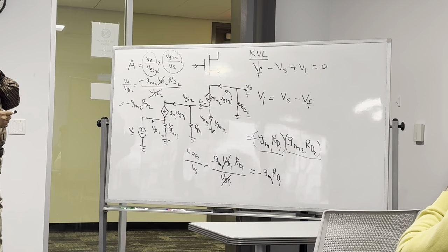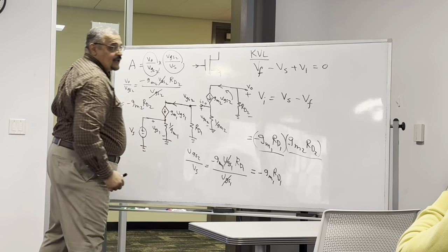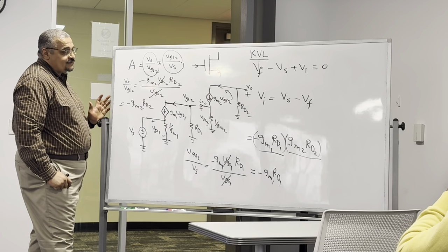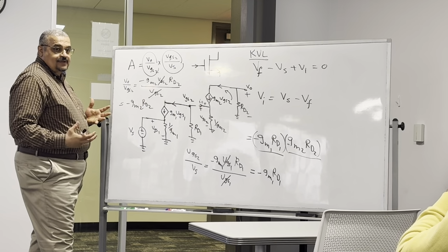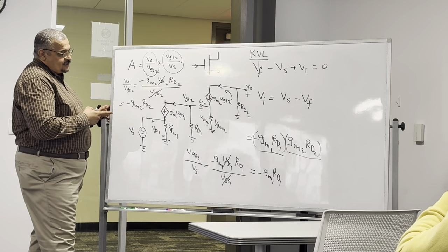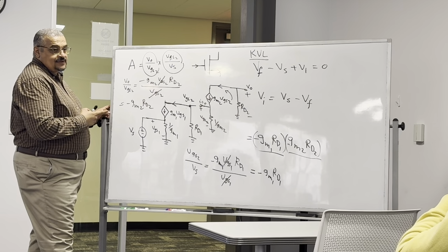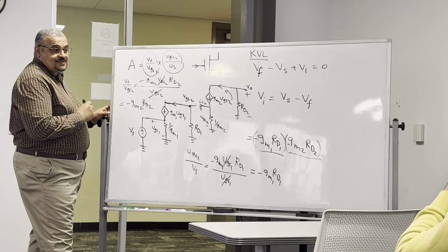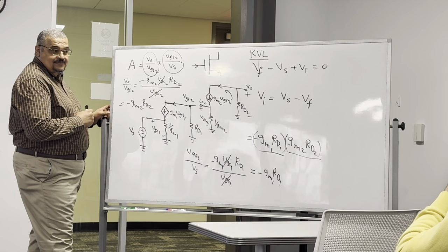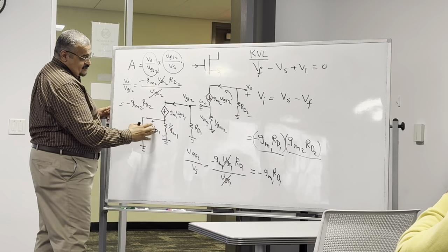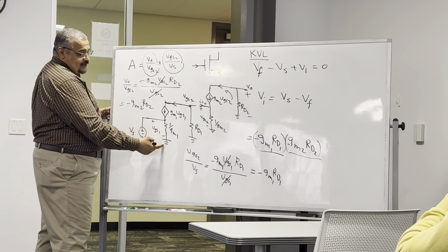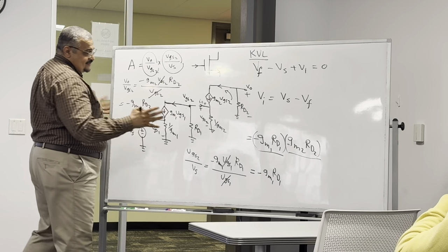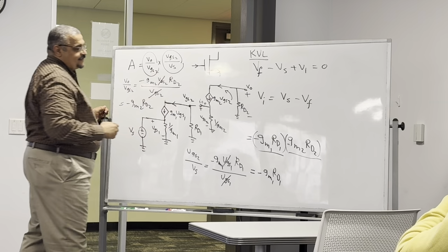Again, if you're not confident, try to use the equivalent circuit and solve it this way. It's going to take longer, but you feel confident. And here I used what model? T model or hybrid pi model? T model, and it makes it more difficult. If I use the hybrid pi model, it's going to be much easier. I told you, if you have a transistor that has the source grounded, use the hybrid pi model. The T model makes you have to think about this, and so on.